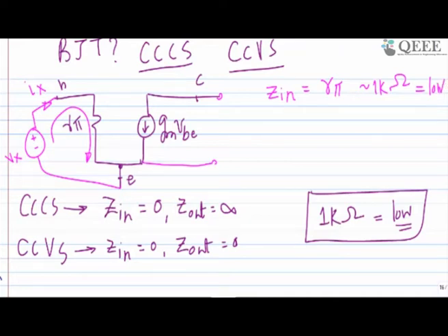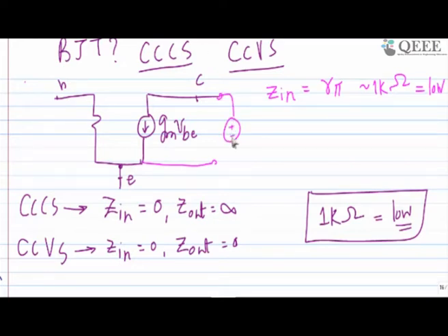Now I want to find out what is the output impedance of my circuit. So if I want to find out output resistance, I'm applying a known potential Vx. I'm going to measure Vx by Ix, and during that time my input will be shorted, right? So if that is the case, base becomes 0, emitter becomes 0, R pi has no influence, and gmVBE becomes 0.